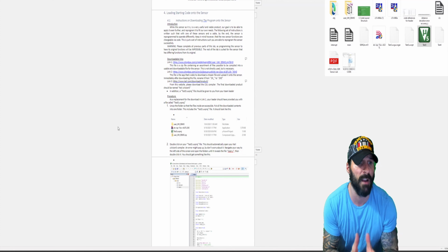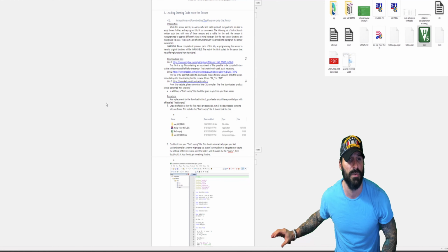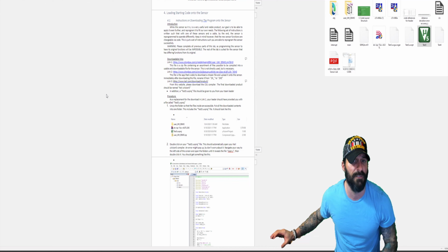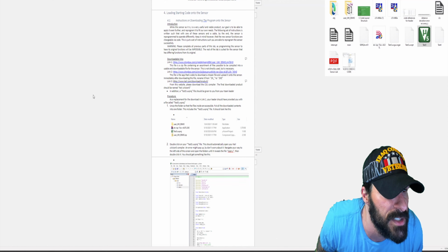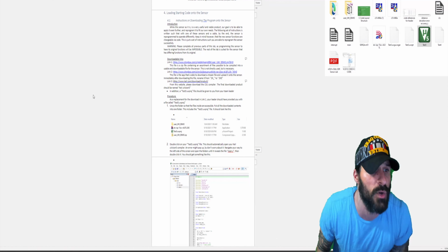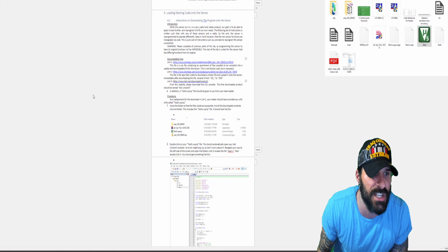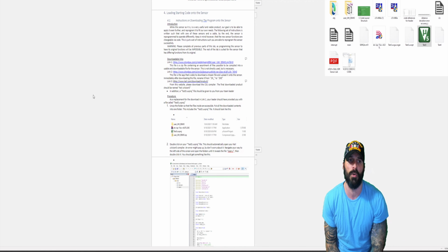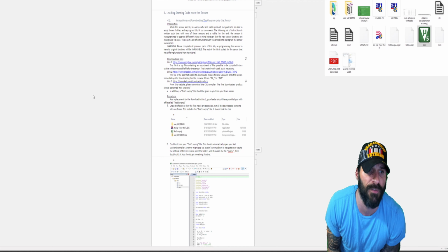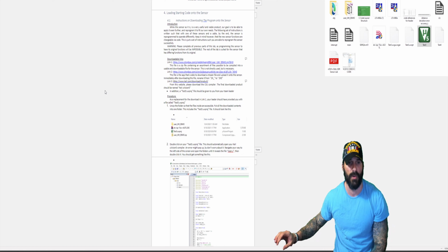So you're going to have to modify the MCU type. Okay, it's very, very important that you modify the MCU type on this system, and then you have to select STC, which is 8F2K16S2, and you have to change the input frequency to 11.0592. And once you connect, the USB port will initialize on channel 340 on a COM, from 2400 to 115200 baud rate.